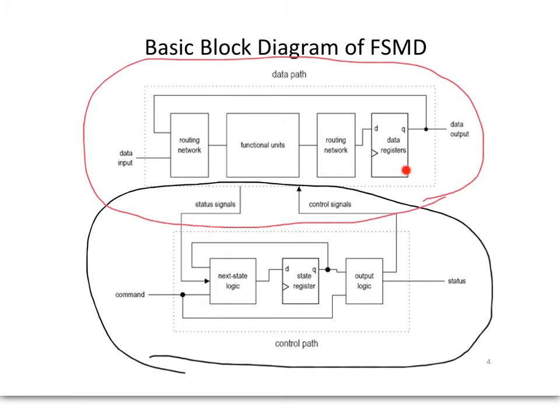And as always, when we build a synchronous system, we have data registers on the output to register whatever logic operations we have and synchronize them against a common clock. And again, the signal is fed back, and we could call this entire block our next state logic, so it looks like the synchronous system we know.